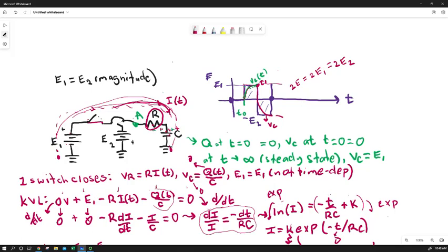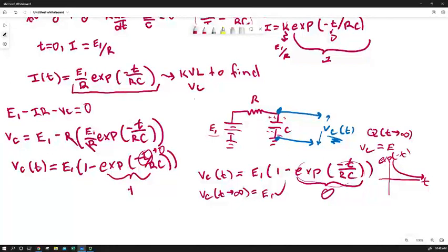We've got an expression that can predict this curve up to C1, and we can predict a time in that curve that we could evaluate R over C. And when we go to look at our plots from our oscilloscope, when we apply a square wave, what we're eventually going to want to do is relate the appearance of the curve that represents the voltage signal over the capacitor to R and C. And that product of RC is known as tau, the time constant.